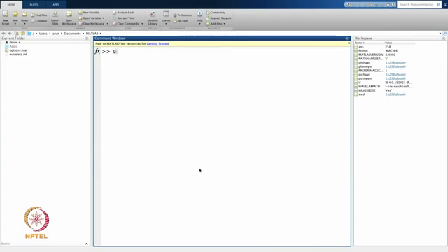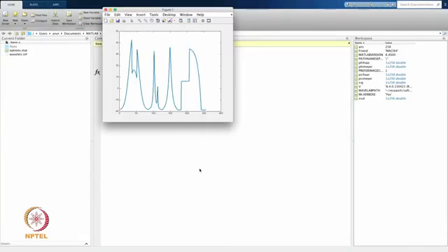For this, we shall take the signal that we had used in lecture 8.3, where I showed you the DWT of a piecewise regular polynomial from Mallat's book, and let us generate 256 observations of this signal, and make sure that this is the signal that we want to analyze. So, this is how it is, and it looks right.